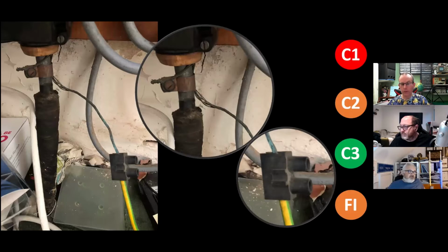Here's an interesting one. So you get a lot of intakes where you get little stringy bits of aluminium connected into sheaths and heads. Now, just be wary, some folks. Don't cut them off, because the BT lines, at the end of their circuits, they would actually run a little small squiggly aluminium cable connected into the DNO as their end of circuit earthing. But loads of electricians have gone and cut them off.